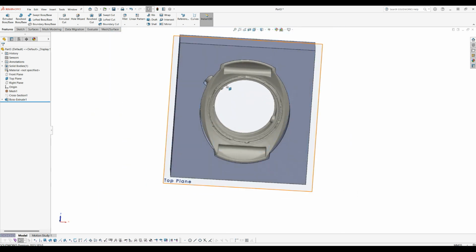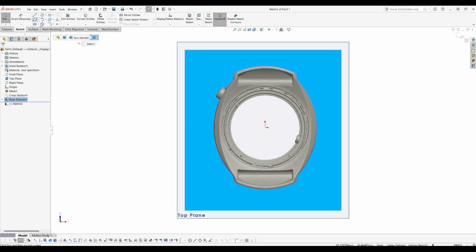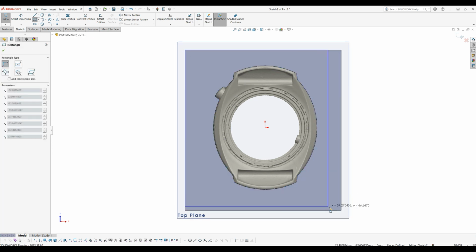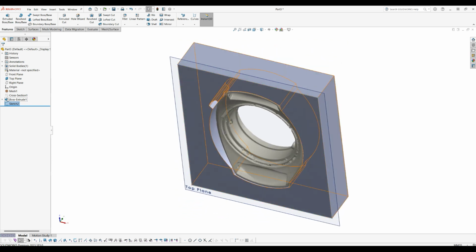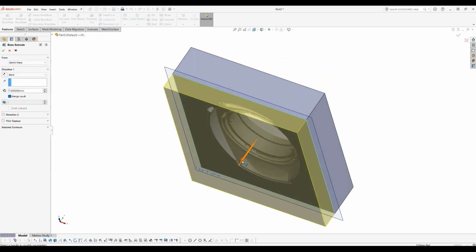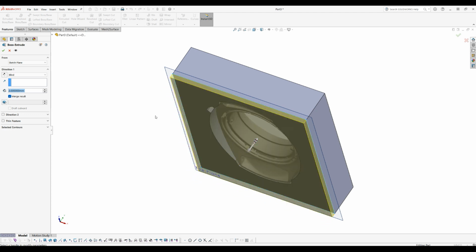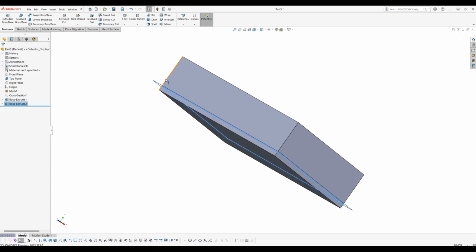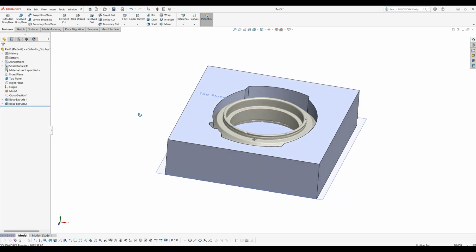Probably I need to close it at the bottom. Maybe you know different approaches. What I'm going to do is just create another sketch. We'll create a solid triangle here that matches my corners. Press OK. And this sketch I will just slightly extrude, something like this, maybe 2 millimeters. And this is how I created my packaging.